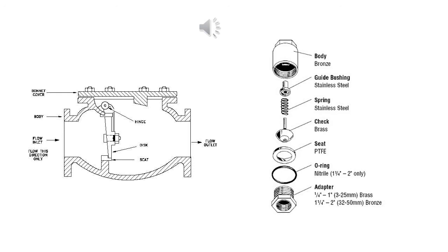Swing check valves are available in either Y pattern or straight body design. In either style, the disc and hinge are suspended from the body by means of a hinge pin. Seating is either metal to metal or metal seat to composition disc. Swing check valve shutoff depends on gravity, weight of the disc, and reverse flow. They are one of the few self-automated valves that do not require assistance to open and close. Unlike other valves, they continue to work even if you lose electricity or the human being that might manually cycle them.